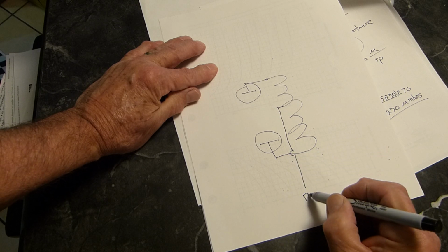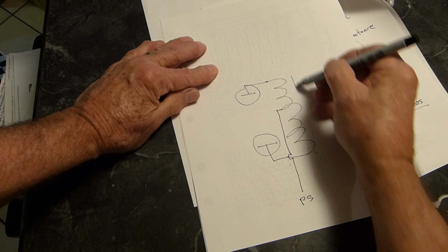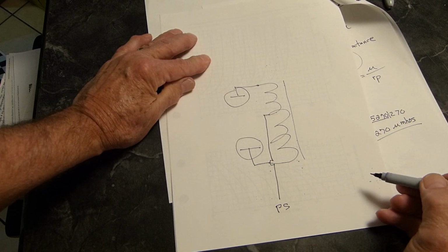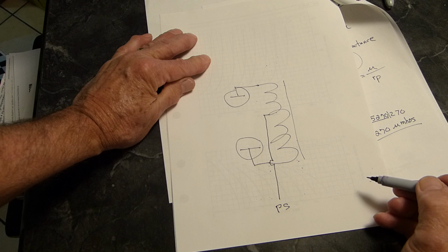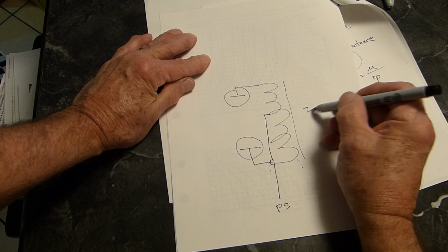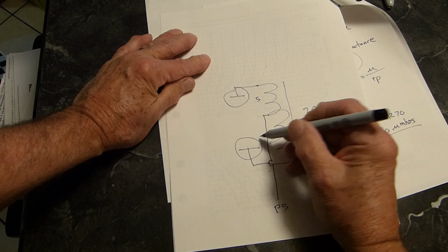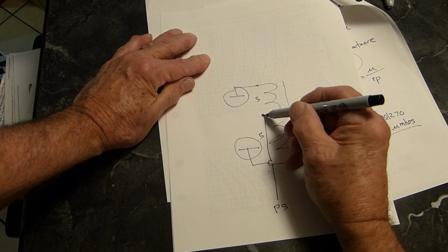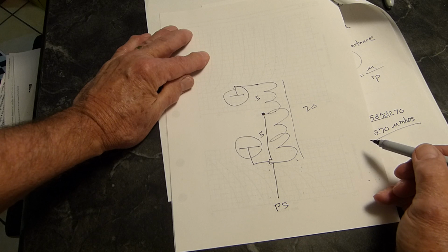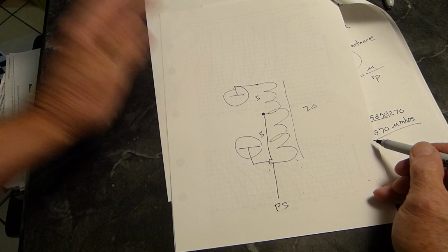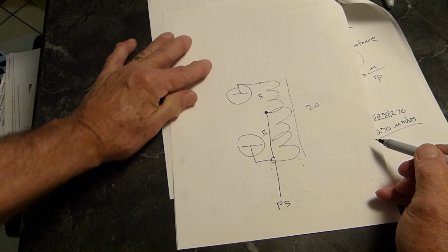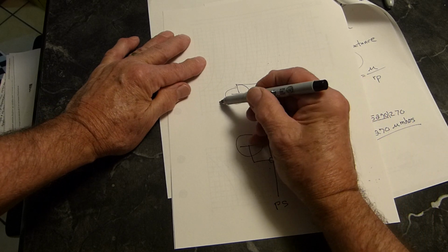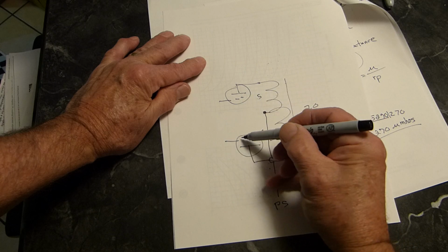this goes to the power supply. If you're overly concerned with the inductance of your transformer, and you've got a 20 Henry here, but you only got 5 here, and you only got 5 here. This point right here is at signal ground, and I don't mean AC signal ground, not like the AC input current, not 60 and 50 hertz, not power supply, but the signal voltage, what's driving the grids of these tubes.